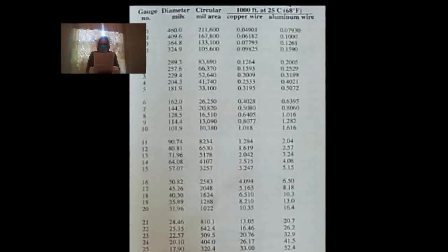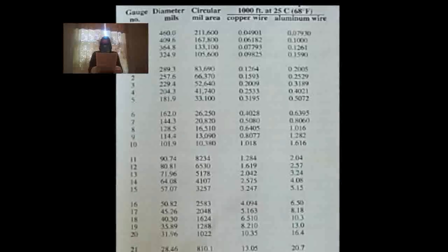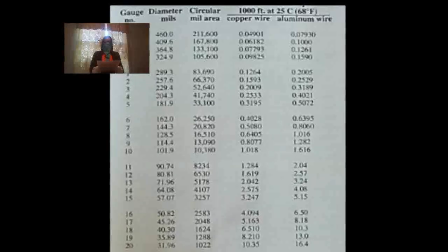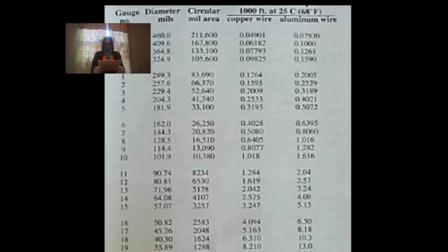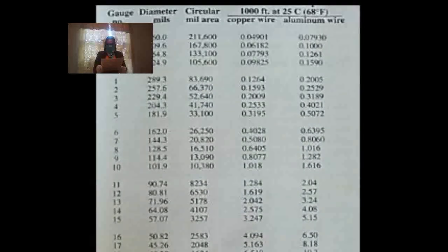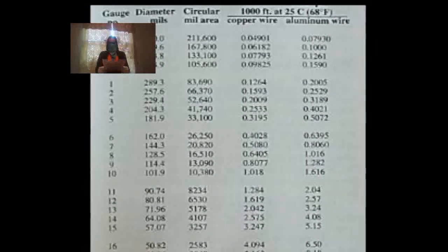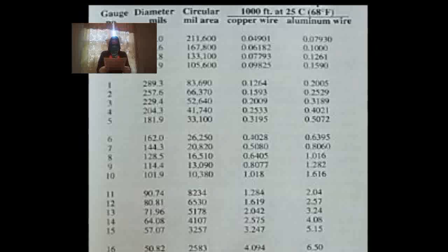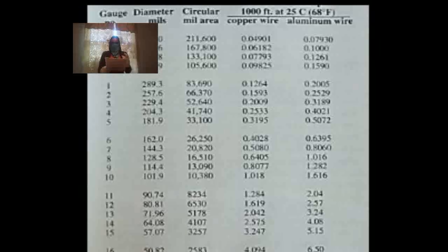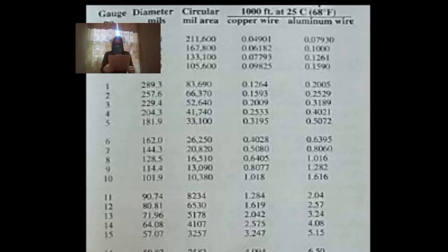This system of wire sizes was developed over 100 years ago. At that time, no one could foresee that the demand for electrical products would make this system obsolete. Some wire sizes are now larger than number 1 conductor. A temporary solution to this problem created the next set of larger sizes. The next 4 sizes developed are 0, pronounced aught, double aught, triple aught, and quadruple aught, or 1 aught, 2 aught, 3 aught, 4 aught, etc.